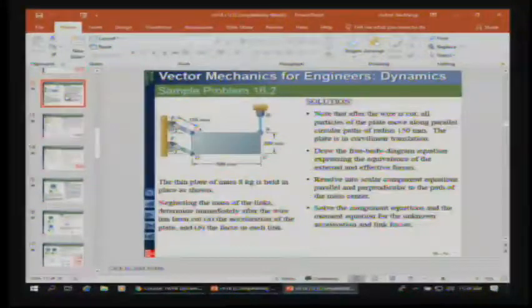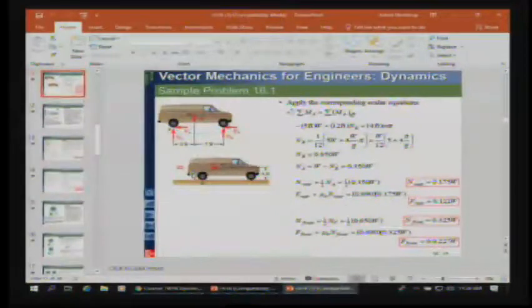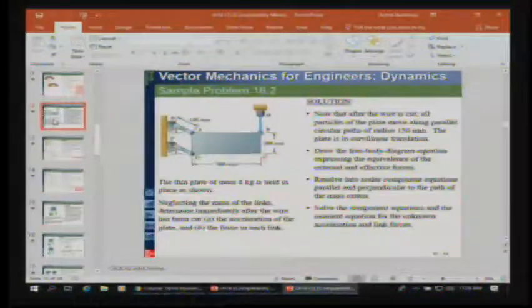So is the W like the weight? Yeah. And if you knew it, you just plug that in. So if you look at that, whatever the weight is, the normal force on the rear wheels is about 17.5% of the weight. But on the front wheels, it's about 32%. So like I said, nearly double on the front what it is on the back. So with any of these problems, always start with a good free body diagram, that good analysis, and then you can see that you have almost all of the skills that you need, that you've been taught previously, to solve these kinds of problems.